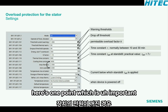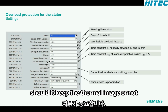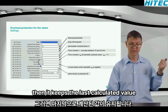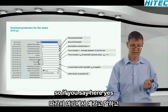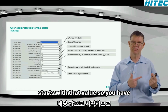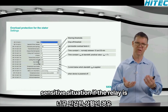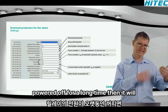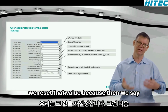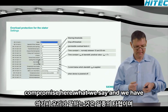Here's one point which is important. If the device is powered off, should it keep the thermal image or not? I recommend set it to on. Then it keeps the last calculated value. So if you say here yes, and if the power comes back, then it starts with that value. So you have rather a too sensitive setting or too sensitive situation. If the relay is powered off for a long time, then it will also clear that memory. After 500 seconds, we reset that value, because then we say, okay, then the temperature of the motor can be anywhere. So it's a kind of compromise here, what we say.